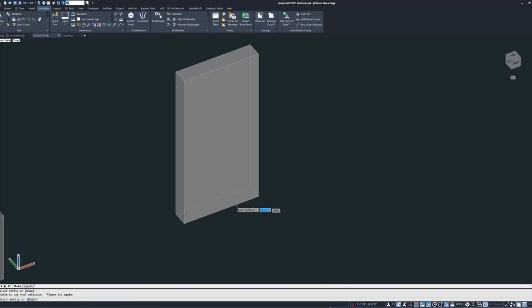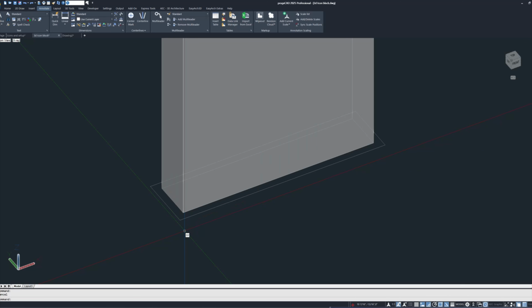Now that the polyline is created, we need to offset it to the thickness of the box. We are using 1/8 of an inch. Now we need to move the polyline down the same 1/8 of an inch below the distance of the void box, so we can then subtract space within the dimensions of the phone.